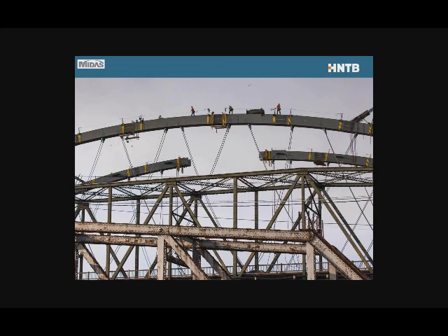This also works for the larger size bridges, and this is really the traditional method of hangers in the US at least. You can see this is the Amelia Earhart Memorial Bridge. Disregard the junk in the front. These are the older bridges, and what you see is the ribs of the new arch bridge in the background. You can see the cables are about to be installed. So these are, I think, like 2.5-inch diameter bridge strand or wire rope, and in pairs.